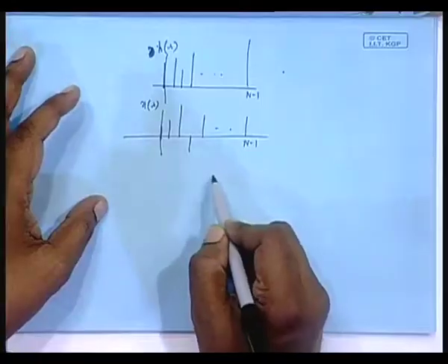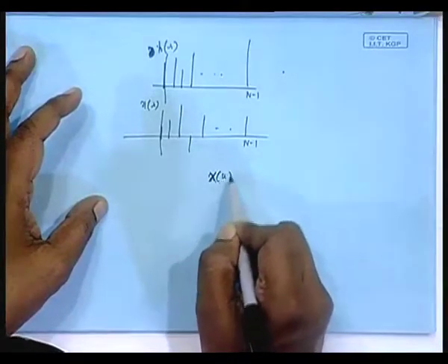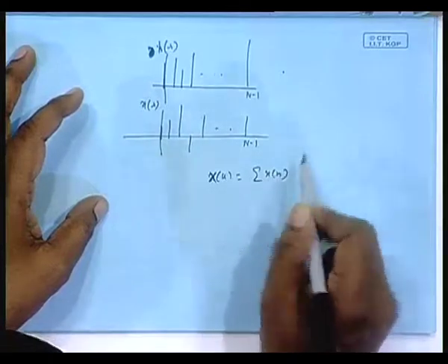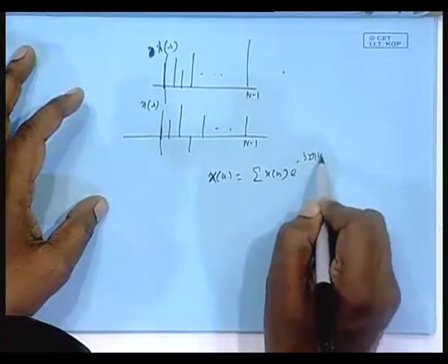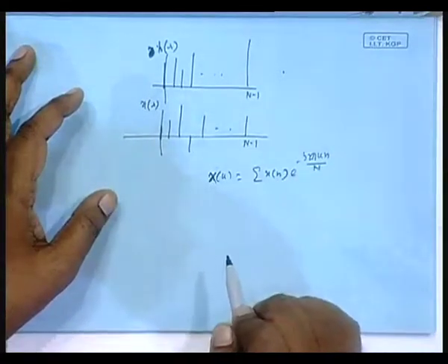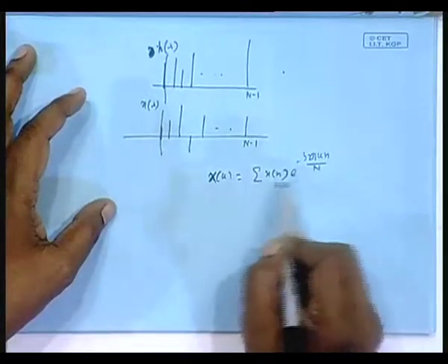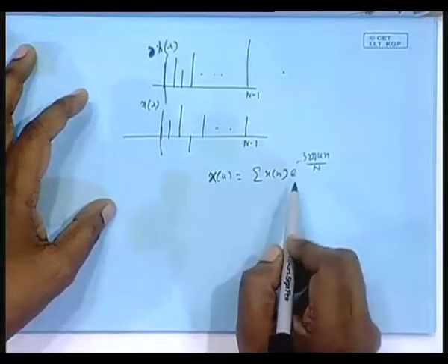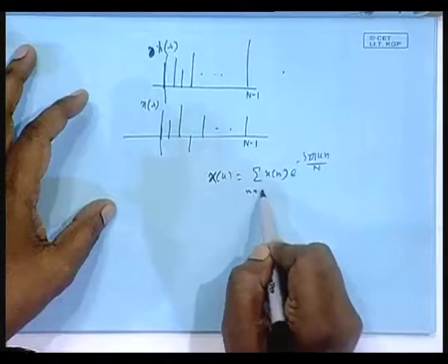And this DFT, you remember why, maybe just 2-3 minutes. Why are you bothered about DFT? Because there are very fast algorithms available. If you see this simple DFT computation, X(k), for each k, how many complex multiplications? Capital N, isn't it?